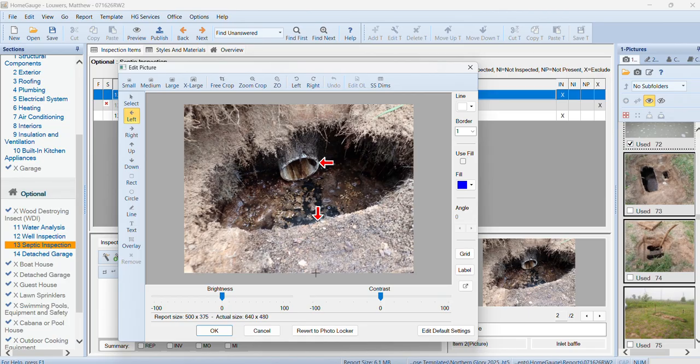This is just a little 4-inch concrete separation wall that holds the solids in over here, so that if you were to release a bunch of water here into the septic, this wall is going to stop the liquid from mixing and causing a big slurry and mixing the solids up in the effluent liquid. So that's the whole design of a baffle.